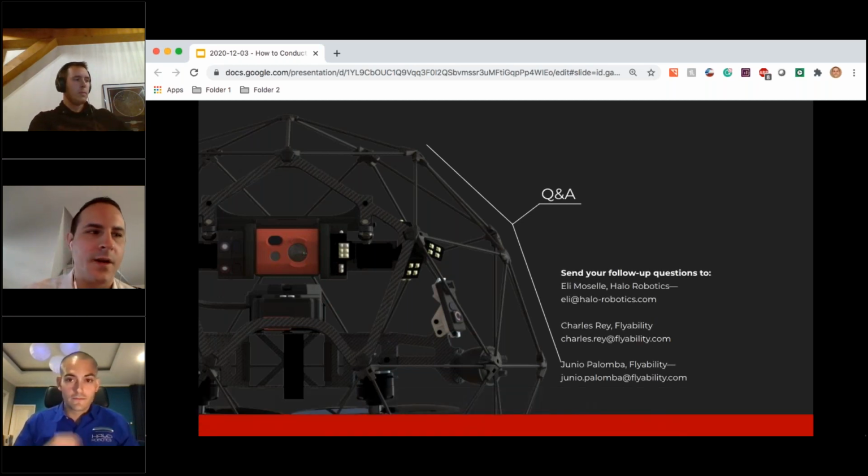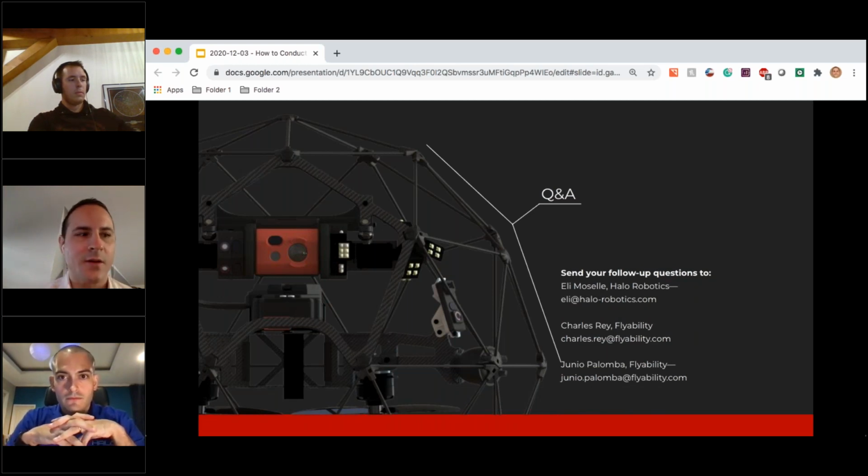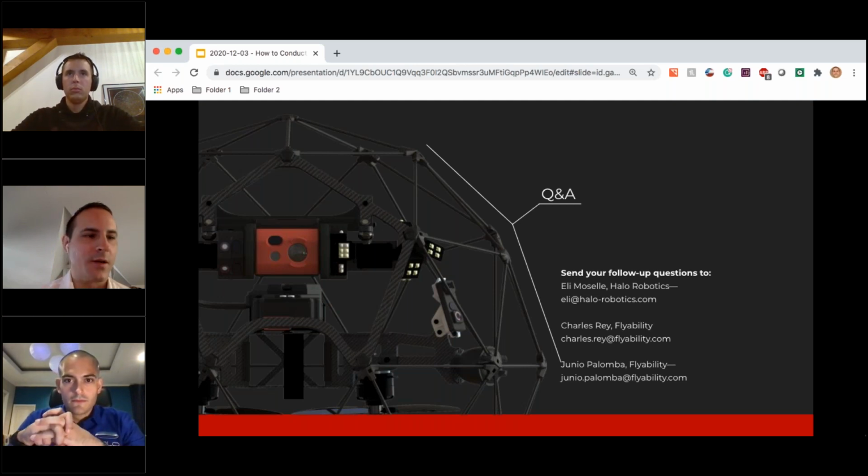One thing I want to note to everyone, and I'll send you a link when we email you with the recording. Eli mentioned the challenge of data localization when you're doing inspections. We actually just rolled out this week on Monday a new version of our inspector software. It's Inspector 3.0 that has a data localization feature so that you can create a sparse point cloud shortly after you conduct your mission. You collect your visual data. It takes 20 to 40 minutes to process and shows you exactly where your points of interest are. So you can pinpoint the location of your defects shortly after you collect visual data with the LEOS 2. So that will be included in the email we send everyone.